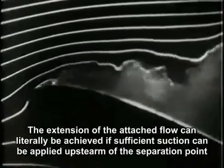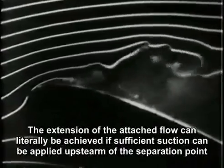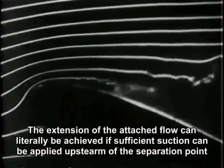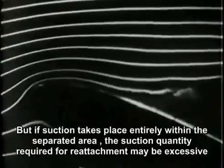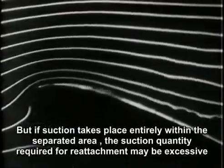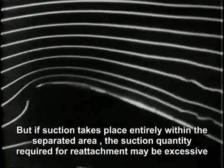The extension of attached flow can readily be achieved if sufficient suction can be applied upstream of the separation point. But if suction takes place entirely within the separated area, the suction quantity required for reattachment may be excessive.